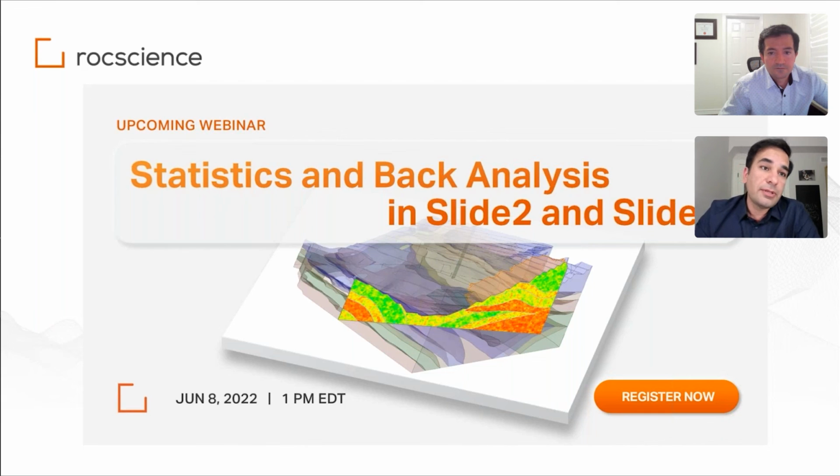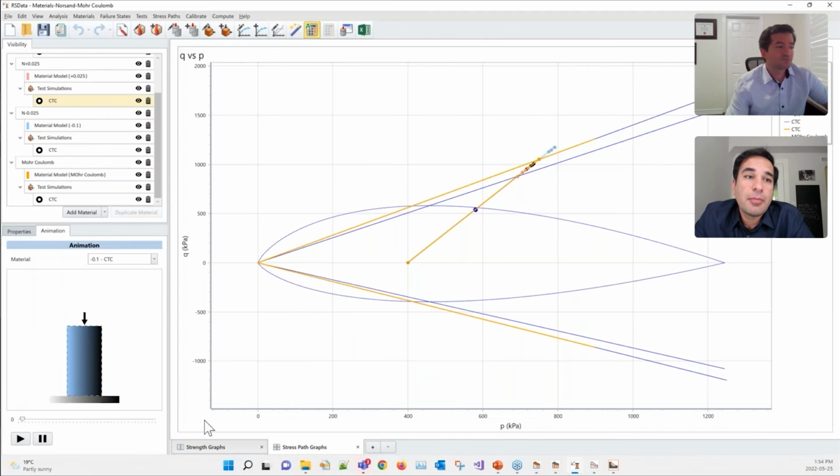If you absolutely don't know your parameters, then some educated guesses is something you can do. If you're looking at a clean quartz type sand, like Ottawa sand, friction angle is about 30, and you can make guesses on other parameters. If you're dealing with tailings, these are angular, they're finer grained, they're very, very variable, so you should absolutely be testing them. If you push me, I'll say, pick a slightly higher friction angle, slightly higher chi, higher slope of the critical state line, probably depending on gradation, but you should be testing them.